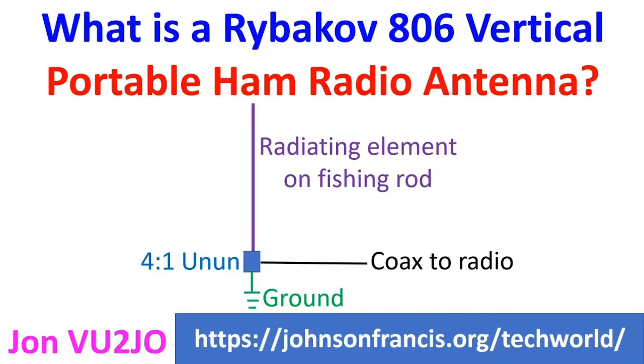A wire length of 7.6 meter can cover from 7 MHz upwards. If 3.5 MHz is needed, wire length has to be increased. Some sort of a ground or radial has been recommended. WB3GCK mentions a 25-foot radiator and a 25-foot radial. Extension of radiator to 53 foot for 80 meter operation was suggested.